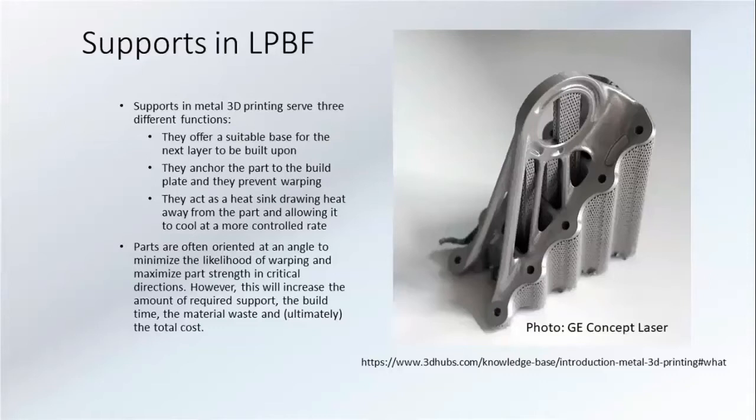That's your rule of thumb. There are machines that can get around that with certain materials in certain settings, but overall that's your rule of thumb for most of your machines. So while I'm designing my part, while I'm doing a topology optimization on my part, I'm usually considering that 45 rule. So I will build the part trying to get as many things that are steeper than 45s, or I'll orient it such that I can. Allows you to get everything back off easier.